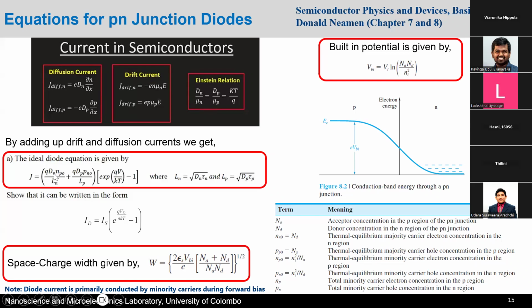So this thing then depends on the diffusion coefficient of the electrons and the holes, and it also has the carrier concentrations in the p-type semiconductor in thermal equilibrium. That's what this zero means. And then it also depends on certain diffusion lengths. This Ln stands for the diffusion length of the electrons in the n-type semiconductor, and similarly for the p-type semiconductor.